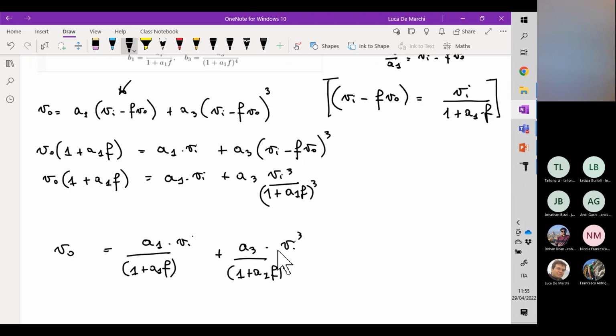The same concept illustrated in this plot can be seen as a shift in the pole positioning in the complex plane. Okay, so the new pole is 1 plus T null times P1, and it is therefore much further apart from the origin.